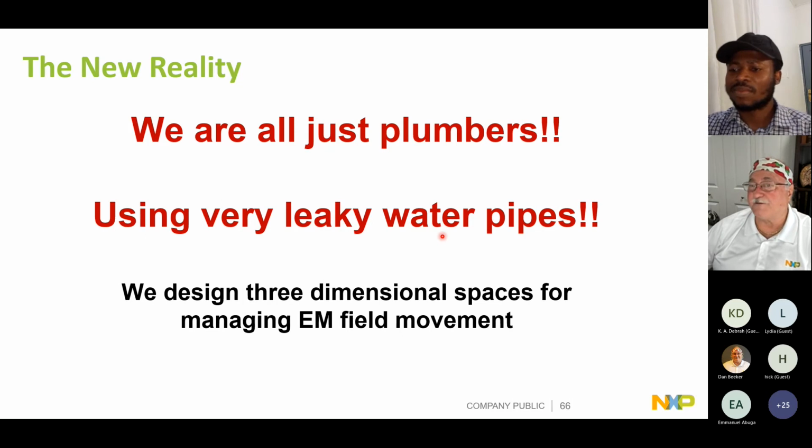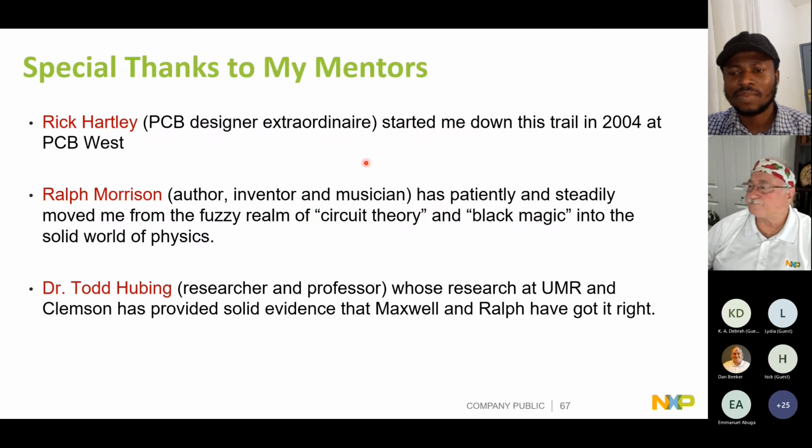The same thing happens with fields. If you don't give it that z-axis plumbing with the signal and the ground via next to each other, the energy will find its way there, but it will spread out through everything. And it will cause problems with the other signals as well as the one.